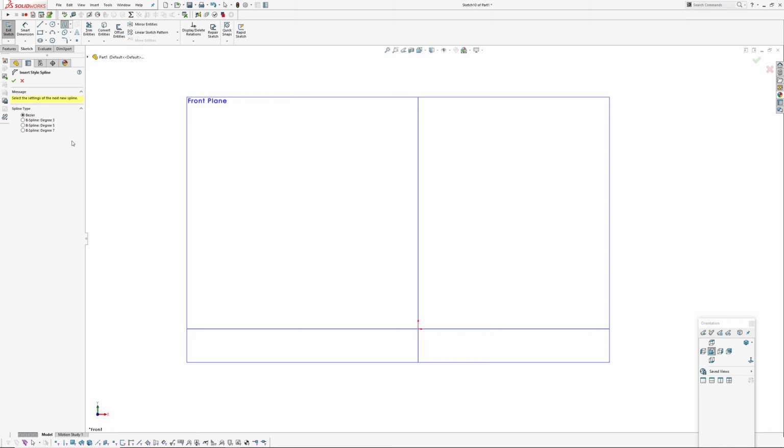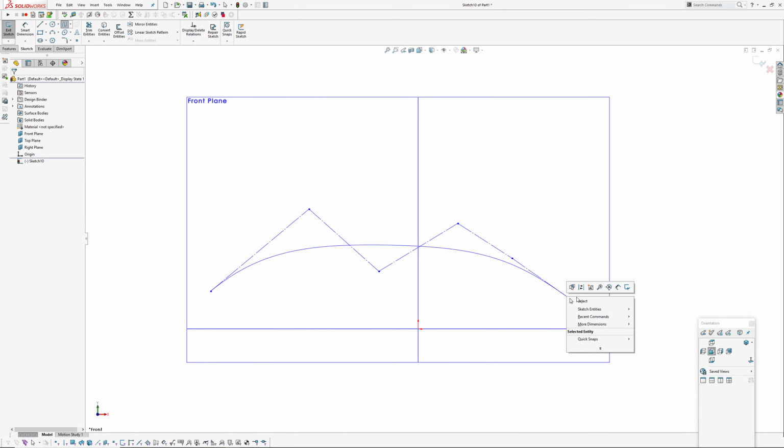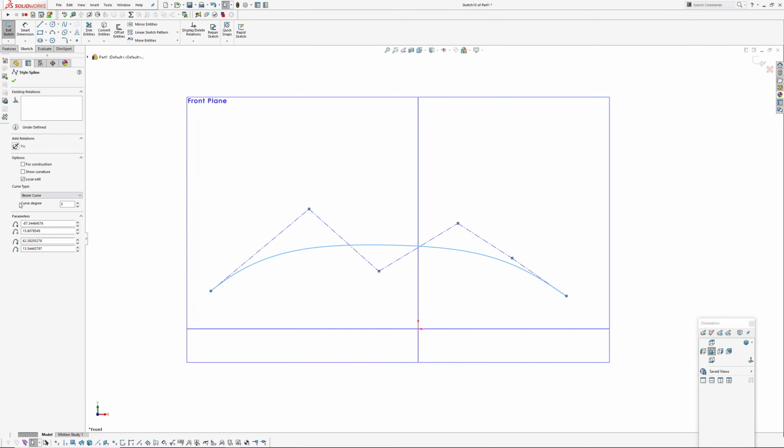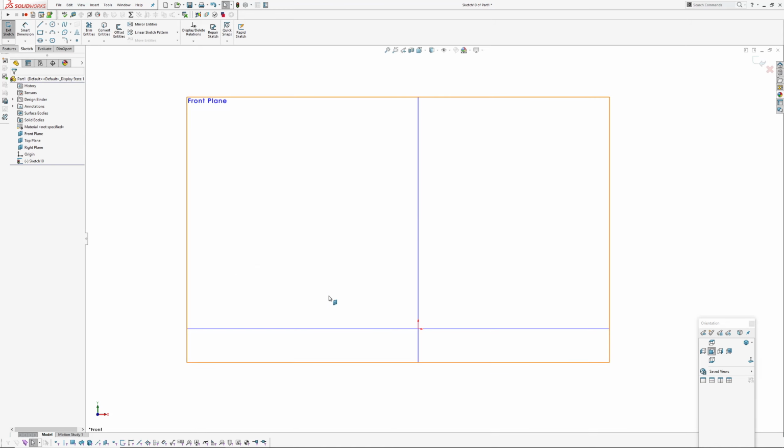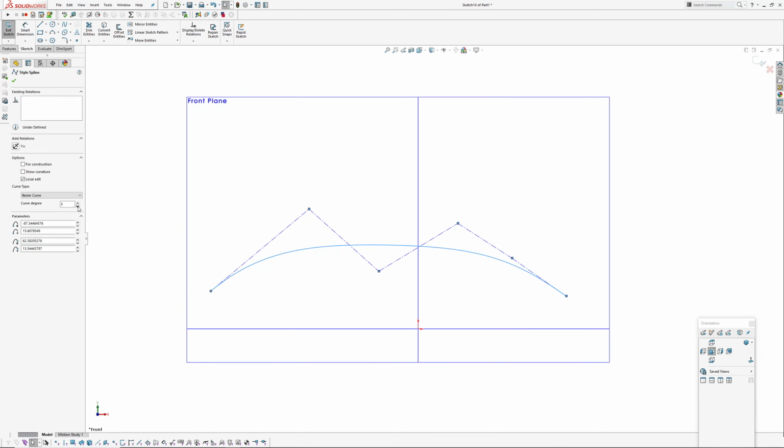So if you go Bezier curve and draw, I've drawn 6 points, so if I pick on that curve, it'll say curve degree is 5. If I go changing this, you can see the control points go down and count. But another thing you might have noticed as I did that: you reduce the curve degree, so the control points are degree plus 1, so 6. As I go down, the curve changes in shape. Where I get to degree 2, I can't get any lower in SolidWorks, which is a line, degree 1.